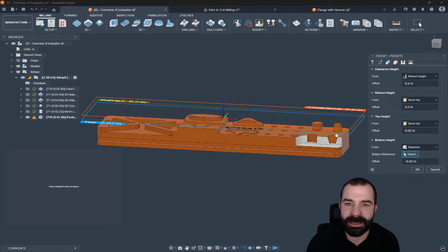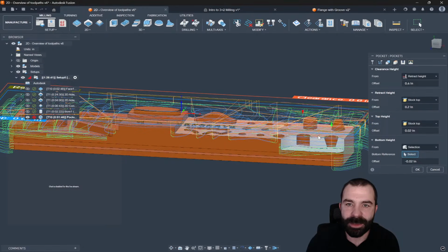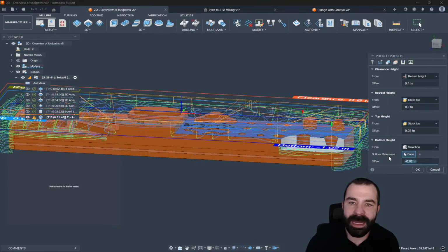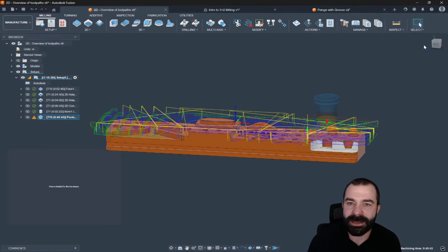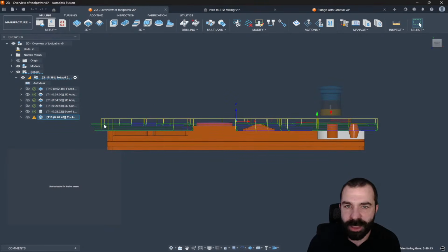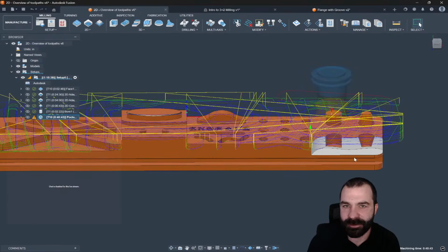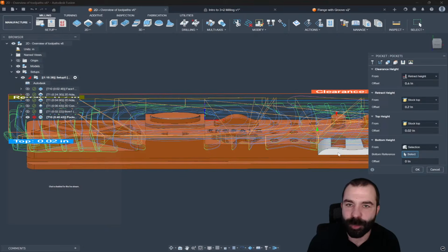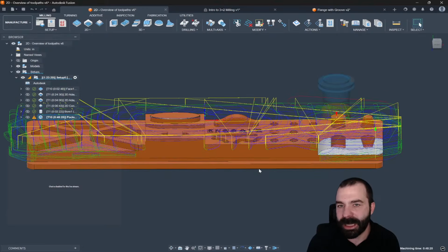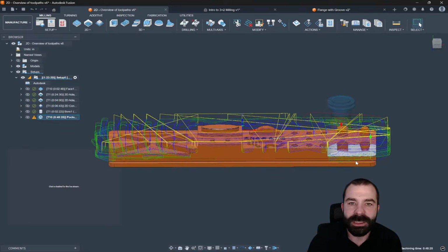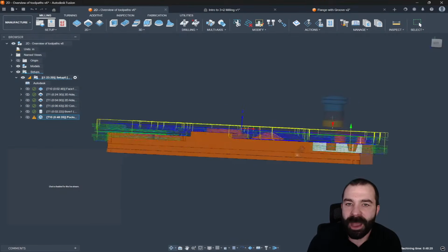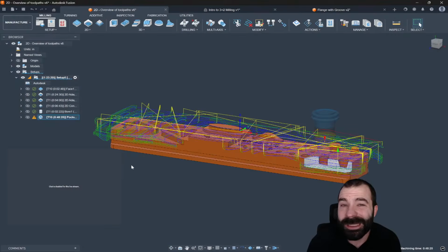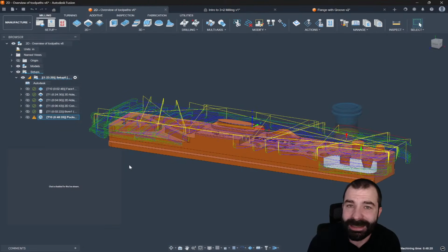I can do a selected surface. We're going to go ahead and select this surface here. Now, I may not want to go past that surface. So again, my offset is now 0. And as you guys are seeing, I am now limiting everything across this part to that one specific surface. So again, changing that one more time. And this is where we get into talking about toolpath efficiency, being able to use a stubby tool to go so deep, maybe go to a longer version of that tool to go even deeper. So again, as you're seeing, I'm not doing much with my heights tab because there's really not a lot that I need to do with that inside of 3D.